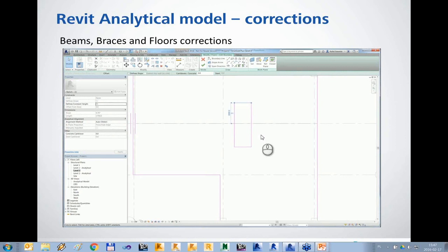And there are two questions for Robot actually. One about instabilities, three different types. Basically, there is no easy way to tell what they are caused by. The first two types are usually lack of support or a mechanism in the structure. The third one is a large difference in stiffness of elements of the model.